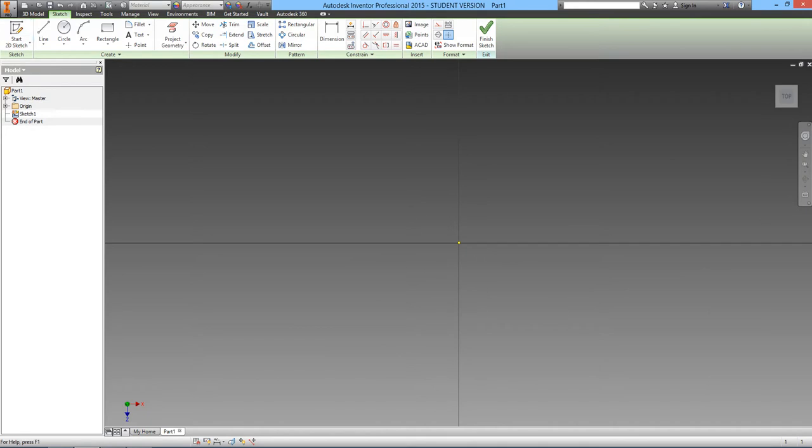And now I'm going to begin by drawing my first line, which is going to be a 5-inch line. Now I know that this is going to come up, but the distance that it comes up is only 1.5. And I get that by taking the 2.5 to the center of the arc minus the radius of the arc, which is 1. And I can go up 1.5. And now I'm going to come in 1.